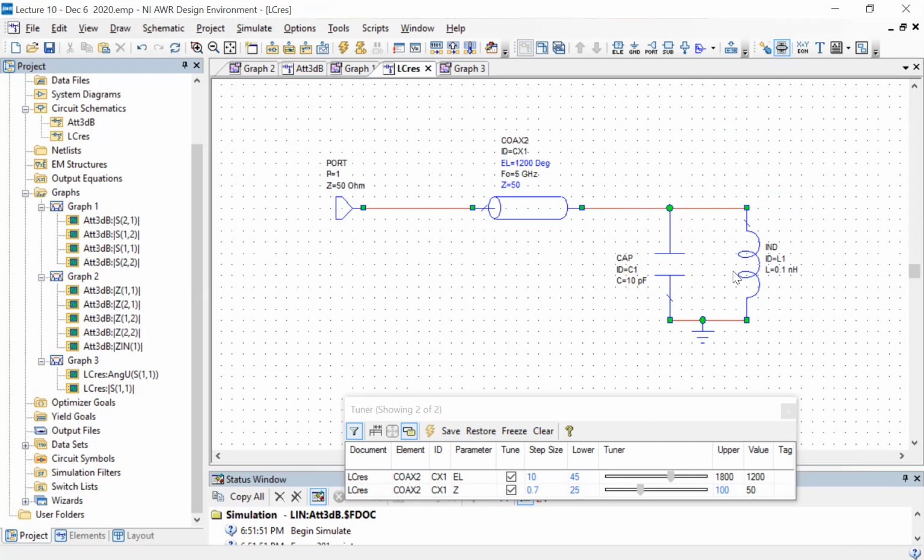Okay. All right. One question is how these switches work. Like they have some transmission line segment which moves around? Well, there are two types. The one which, for example, we have in our lab uses a solenoid to move things. So it's actually a small coil which moves a piece of transmission line up and down so that it makes or breaks connection.